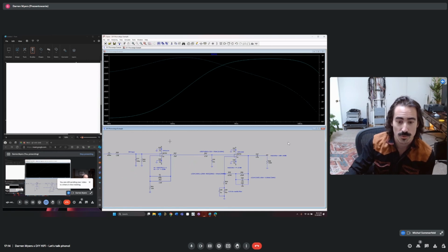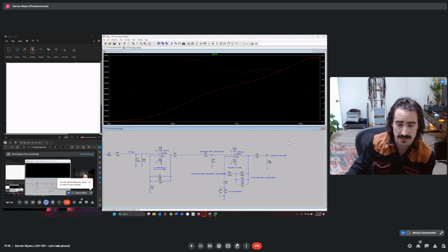And the first spec that jumps out for U4 is going to be noise. We are very, very concerned about noise, because of how much gain follows this op-amp. Whatever noise is at this node is going to be much larger at 1 kilohertz, 100 times larger on the output.